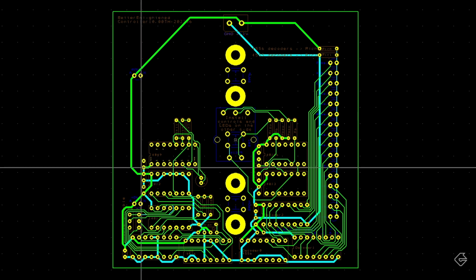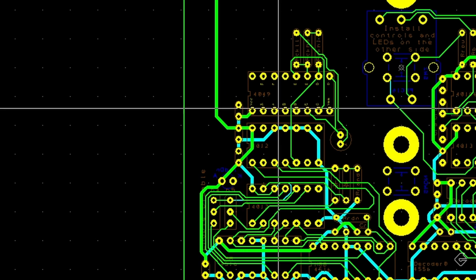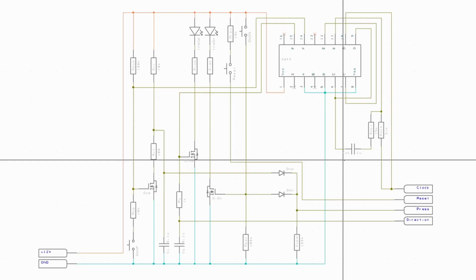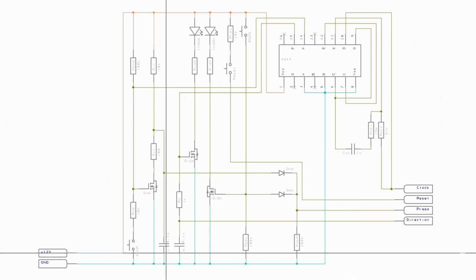And as I'm doing this, you notice I'm also adding those bypass capacitors, which are these ones right over here. In the schematic, this capacitor over here looks just like every other capacitor, just like down here, but this is a 1 microfarad capacitor. And since we're using through-hole components, the 1 microfarad capacitor actually is a physically different package than the other capacitors in our circuit. It looks like this. It's one of those cylindrical monsters that actually look a little different. So we got to make sure that we accommodate for that on our PCB.